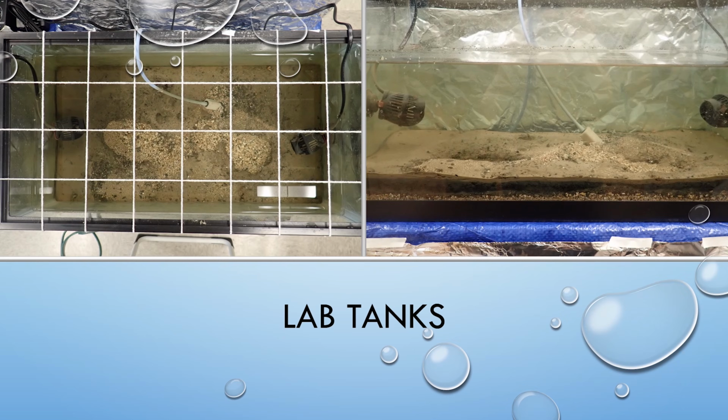So these are 15-gallon standard fish tanks that we used for our lab testing. The tanks were cleaned, and then we added a layer of wash sand, then clay, and then pond sludge that had been frozen and thawed. Two of these side pumps were set on a timer to be on for 15 minutes, and they were added to a controller to alternate their on times every 10 seconds. These pumps ran once every 6 hours just to give a general mild bottom lateral movement over the sludge.